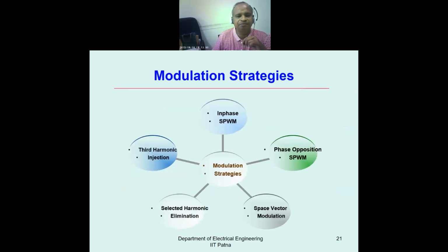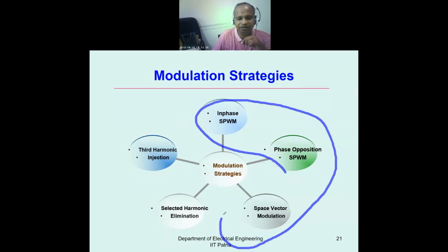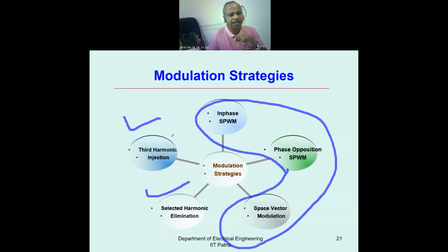So this way, there are different advanced modulation strategies: in-phase PWM, phase opposition, space vector, selected harmonic elimination, and third harmonic. These are the advanced techniques which we use. We will see these three, and these two you can read. Third harmonic injection is an extension of this one.